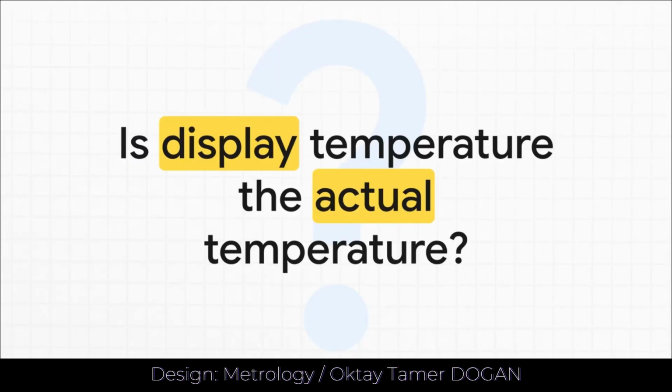All right, Section 1, the climatic chamber challenge. When you place a critical, expensive component inside a testing chamber, precision is literally everything. But I want to hook you immediately with this question right off the bat, because we really need to debunk the myth that a climatic chamber is just a perfectly uniform box of hot or cold air. The display panel on the front might confidently declare that it's exactly 85 degrees Celsius and 85% relative humidity inside. But is that actually the temperature of your product?